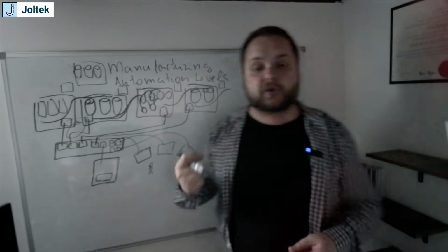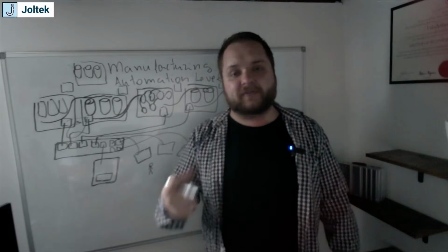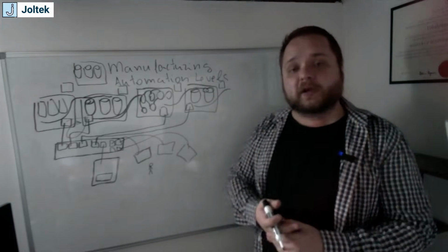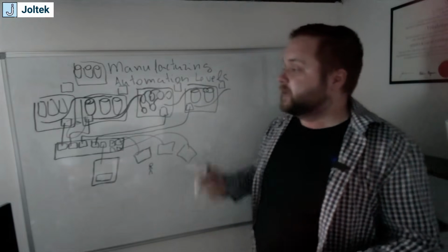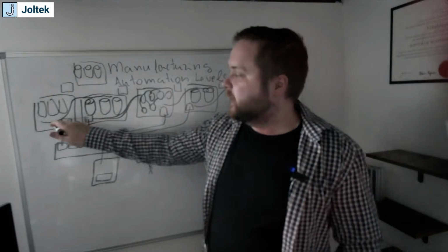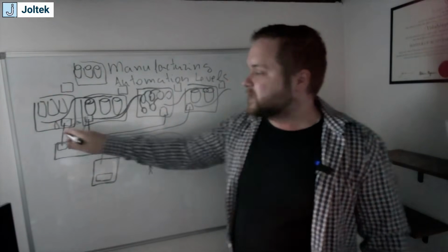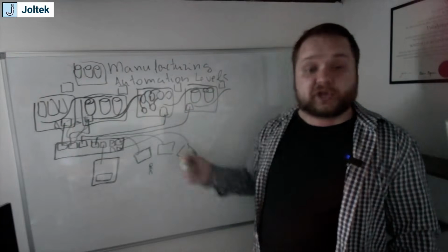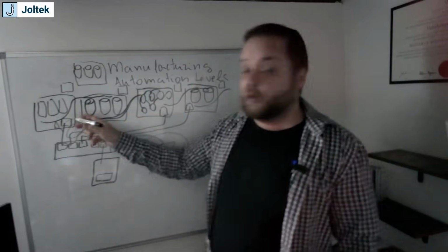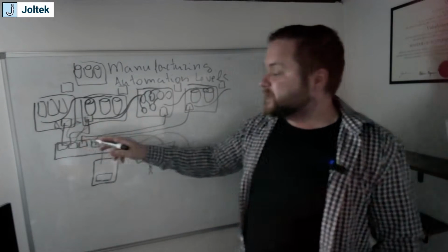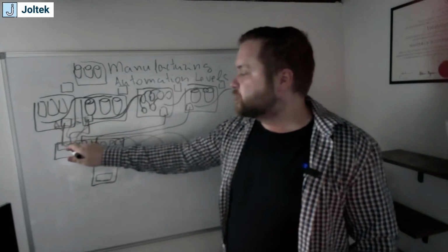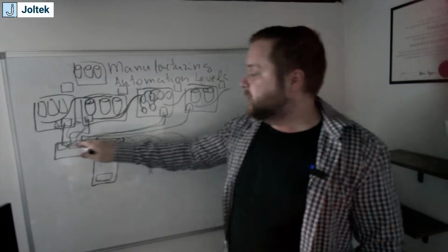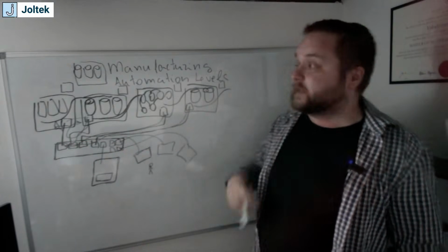And of course, depending on how you do your subnetting or how you set your VLANs, you may not, first of all, have those IP addresses available, but you might also run into traffic bottlenecks. So for example, if this PLC in this specific machine sends the signal that it needs to stop or shut down the process because there's simply overflow of product, and it's on the same network, the traffic is going to travel to all of those ports, right? Because again, it's going to allow it to talk on the entire subnet.